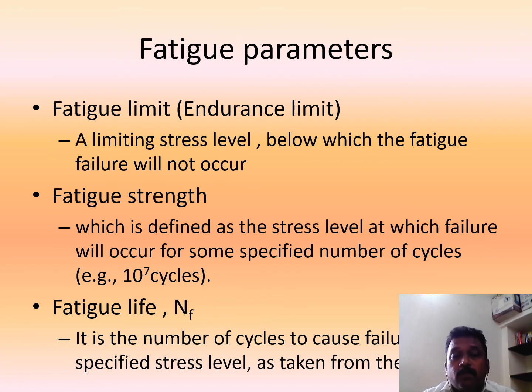So as I told, what is the fatigue limit? That is also called the endurance limit. It is the limiting stress level below which fatigue failure will not occur. So if you apply load up to this level, failure due to fatigue will not occur, which is called the endurance limit. When the load applied for that number of cycles is beyond this limit, the endurance limit, the material will fail due to fatigue.